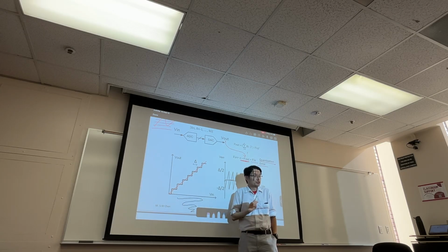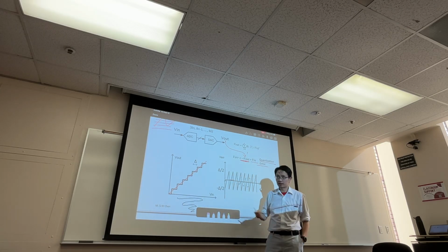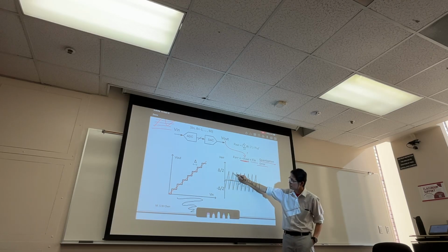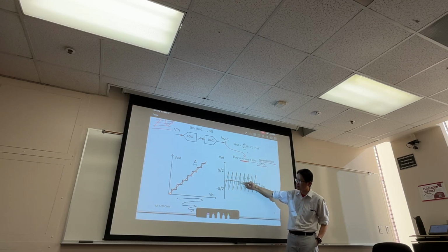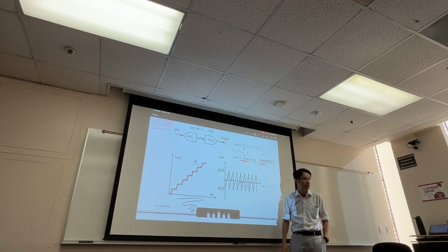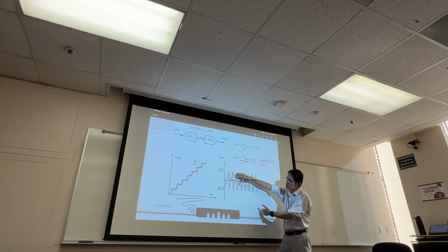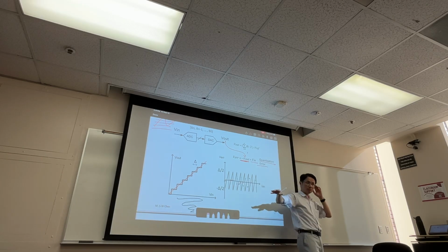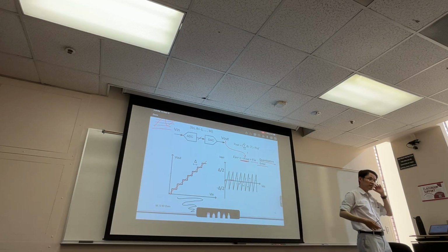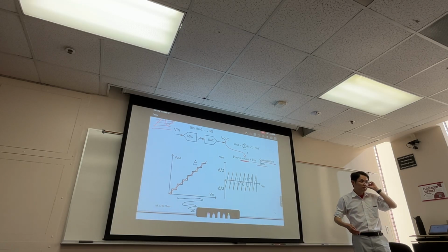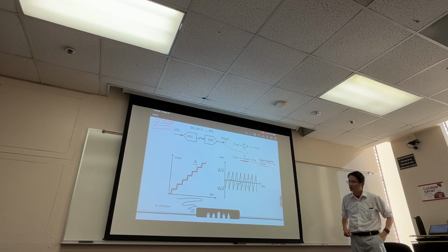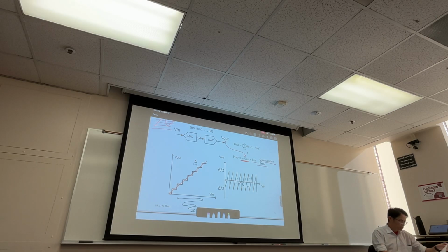Is my assumption kind of correct, that you look at the errors, it's like you randomly sample all these error signals, so they'll be roughly uniformly distributed between plus minus delta over 2. Do you kind of see that? Of course, this really depends on your input signal characteristic, but most of the time, this is a good assumption.